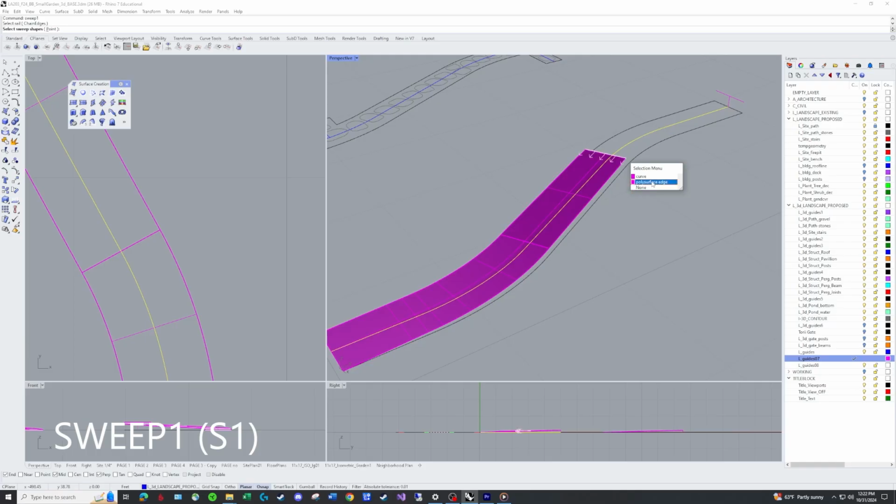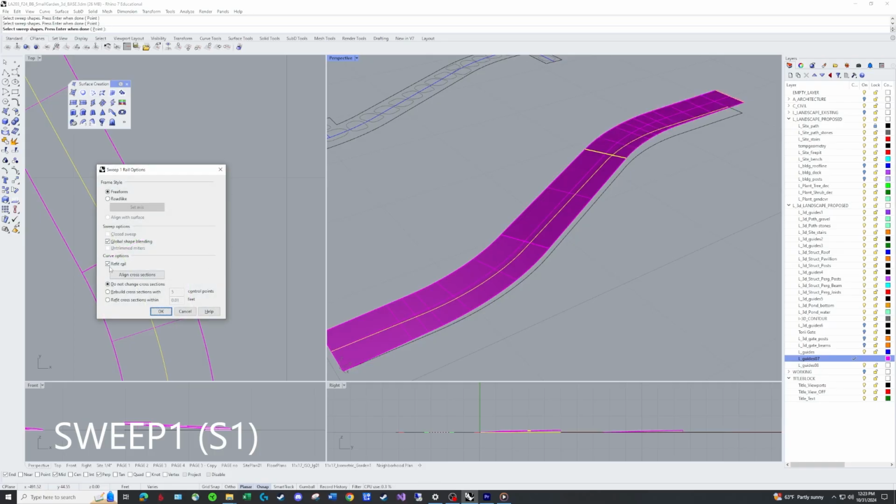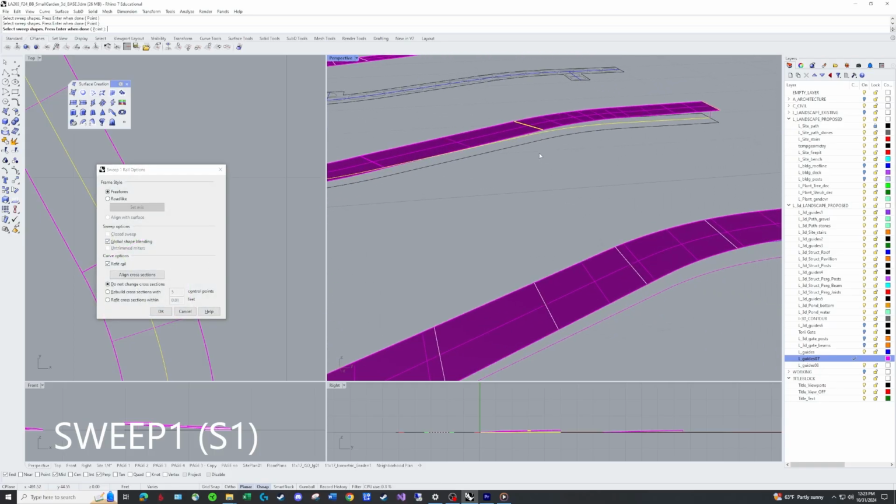Anytime you're trying to connect two surfaces together, occasionally, and actually quite frequently, the surface will deflect away from the curve that you had as an input, and so you need to make sure you always use the surface edge if you can. I don't think there's any difference between these two, but I just want to highlight that it's giving us an option, so use the surface. Got that one, and then I got this one, and I hit enter, and again, let's take a look at what this one does.